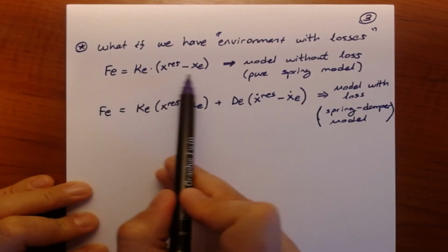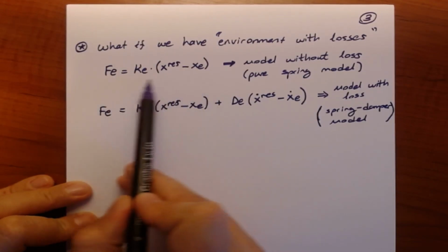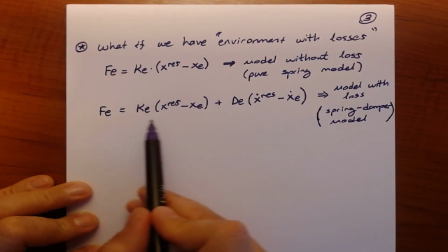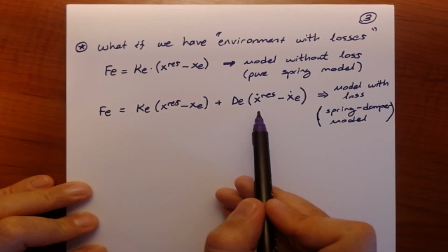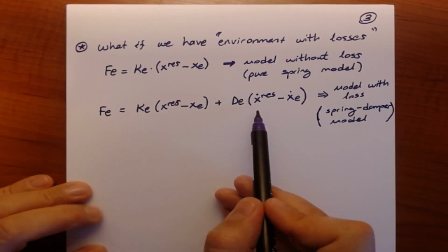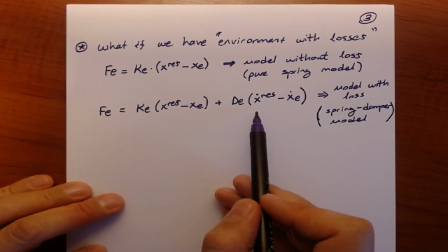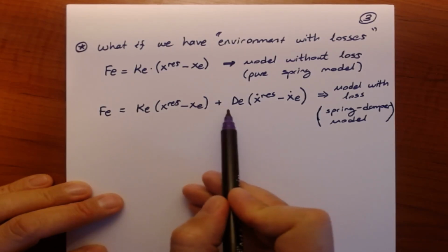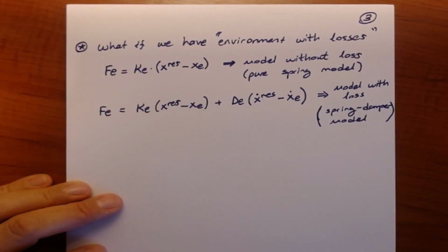Now, once again, this model is more realistic than the previous model, even though in most of the applications the previous model would be sufficient, would help us to carry out the force control. If you stick with that model, both the derivation will be easier and the control performance will be improved in exchange of one detail, that here you have to also be able to measure the damping in the environment, which is not a very easy task.